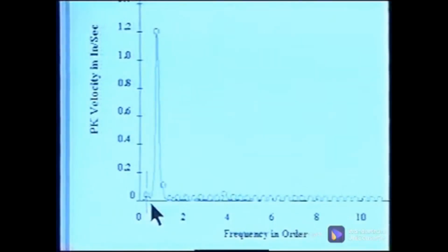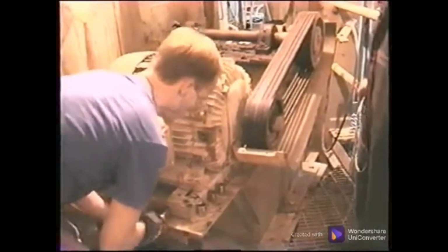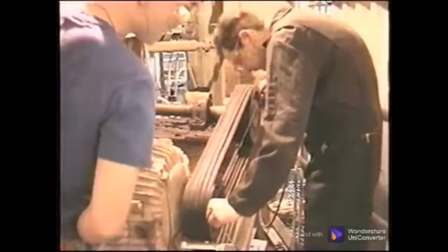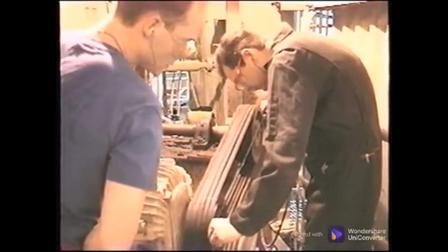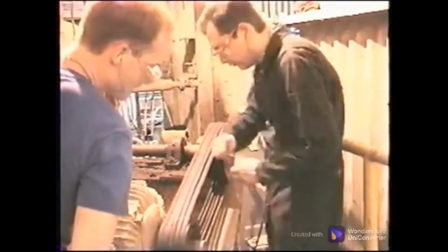Calculate the belt frequency, realizing that multiples of it are most likely to appear in spectral data. Use enough resolution so that belt frequency harmonics will be separated from other energy, such as turning speed of one of the shafts. Check and correct belt problems before doing other work to minimize vibration, such as balancing. Belt-driven equipment can run smoothly, but like other power transmission sources, it requires a conscious effort to overcome compromises and keep the machine in optimum condition.